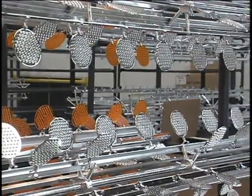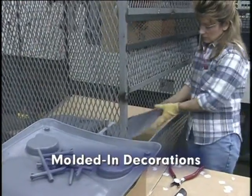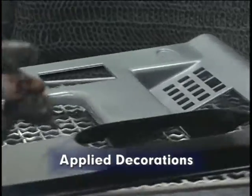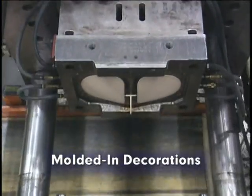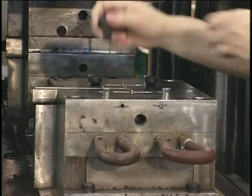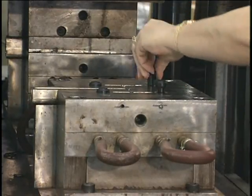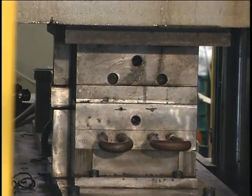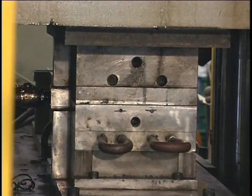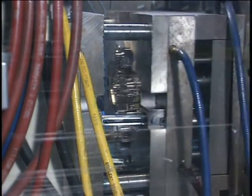The methods of decorating molded parts include molded-in decorations and applied decorations. Molded-in decorations are those machined into the mold, such as textures, or by implant, as with two-shot molding, where an insert is placed into a mold and then molten plastic is injected around the exposed areas of the insert, creating the part. Even pre-colored plastic resins are considered molded-in color.